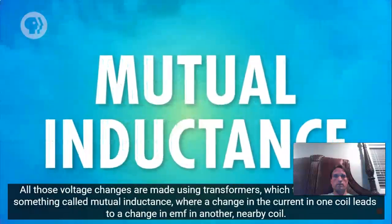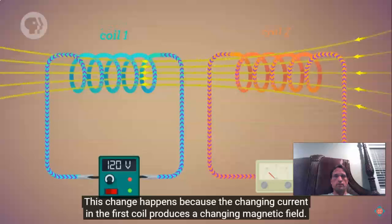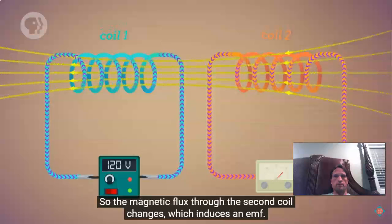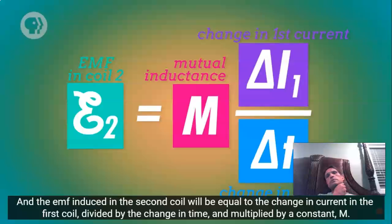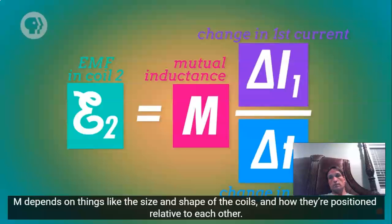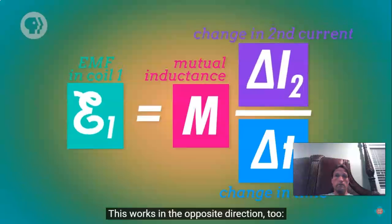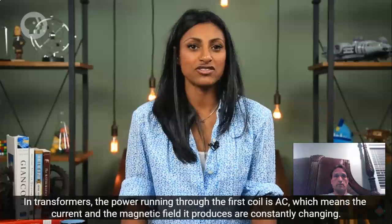where a change in the current in one coil leads to a change in EMF in another nearby coil. An EMF is the same thing as voltage. This change happens because the changing current in the first coil produces a changing magnetic field. So the magnetic flux through the second coil changes, which induces an EMF. And the EMF induced in the second coil will be equal to the changing current in the first coil divided by the change in time and multiplied by a constant M. M depends on things like the size and shape of the coils and how they're positioned relative to each other. This works in the opposite direction too. A change in the current in the second coil will induce the corresponding EMF in the first coil.